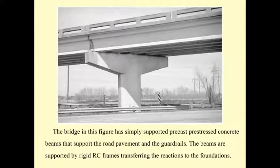Okay, and also the beam and the floor and the guardrail have their own weight. The weight of the beam and the live load are going to act on the beam as a uniformly distributed load, and then the load from the beam will transfer to the beam of this frame.